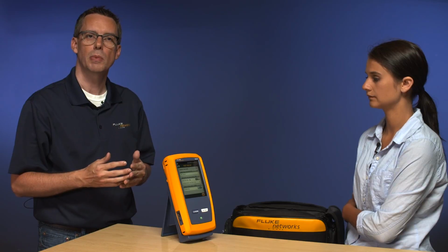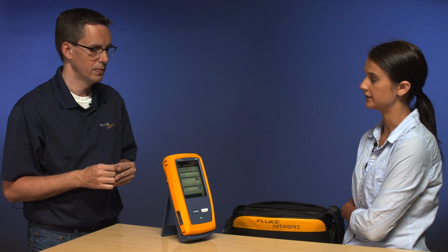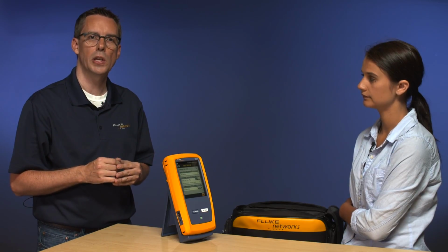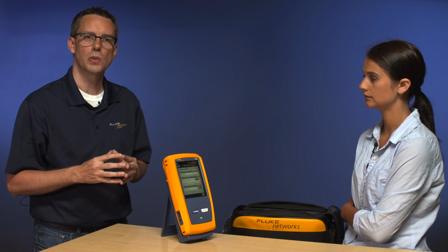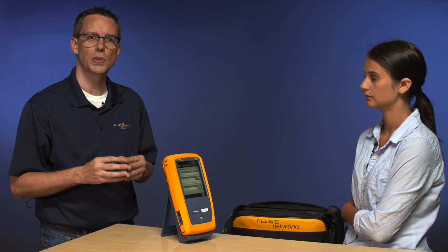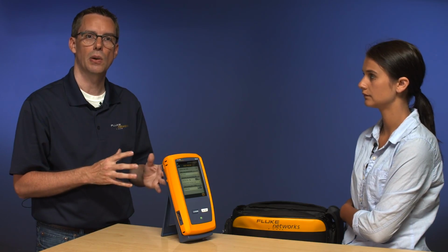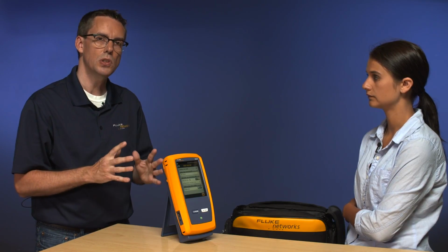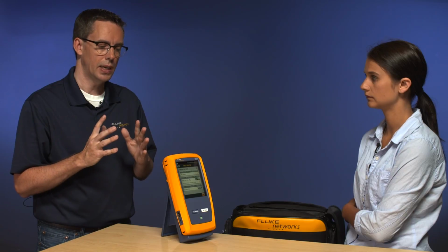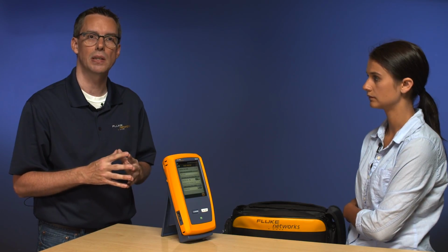So just below the test limit, you'll see store plot data, and we're going to leave that on. Why would you leave plot data on? You know, that's a very good question, and it's a question I get a lot of the time. If you're doing alien crosstalk testing at Cat6 or Cat6a levels, we need that plot data. So if you turned it off, you'd have to end up retesting all these links. Well, we're doing Cat5e today, so maybe we should turn it off. No, if you turn it off, you're going to disable all the pretty graphs that show up on your test report, which the customer is expecting to see.